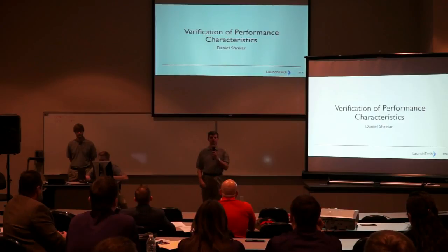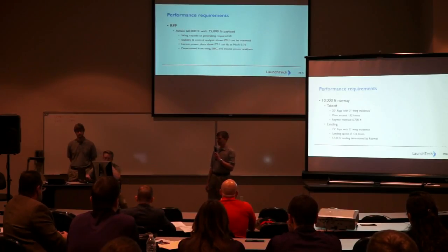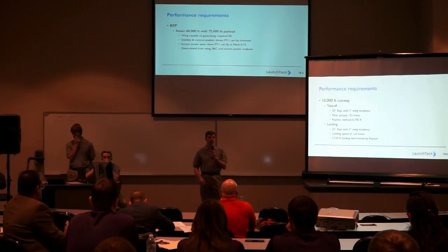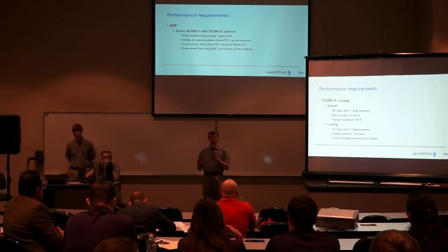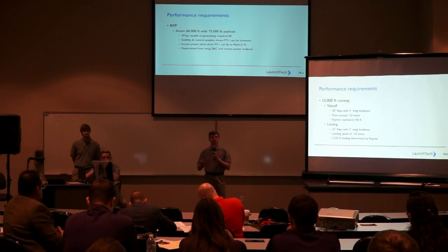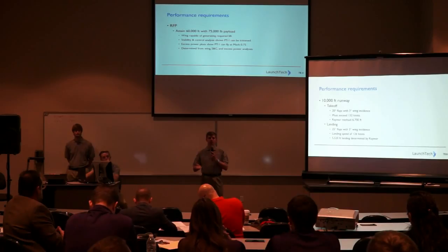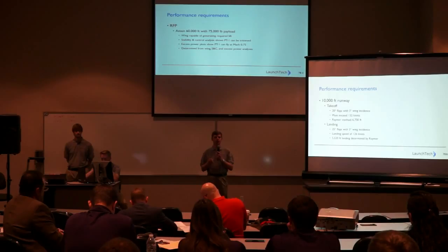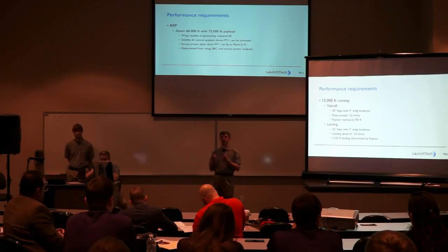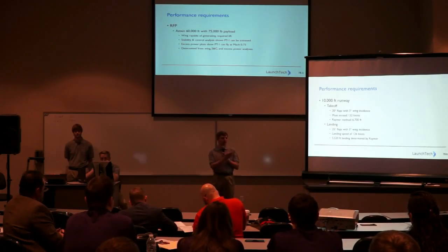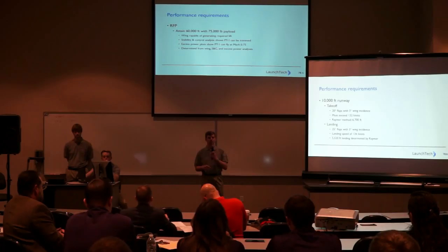Now the verification of the performance characteristics. On the primary screen, our requirement is to achieve 60,000 feet. This is our most important requirement. For 60,000 feet flight, we first analyzed our wing and verified that it could achieve this altitude and hold the PT-1 there. Additionally, from our stability and control analysis, we verified that we could trim the aircraft at 60,000 feet. And from our excess power plots, we determined that the PT-1 has an excess of power and can maintain this altitude.